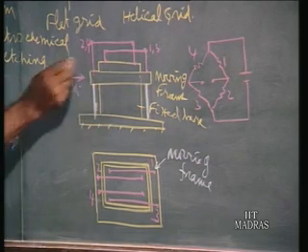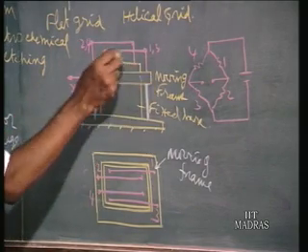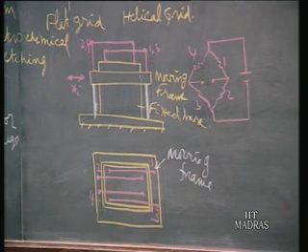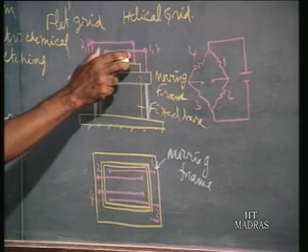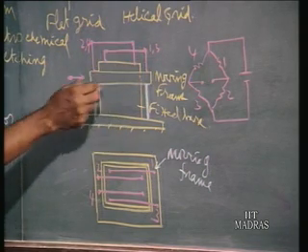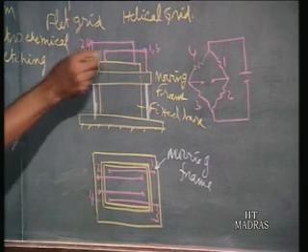This motion of the frame is measured using 4 wires, wire 1, 2, 3 and 4. The wires are fixed in such a way that they are elongated, pulled a little, and then fixed to the pin. In the assembly condition you have to assemble the wire under strain.